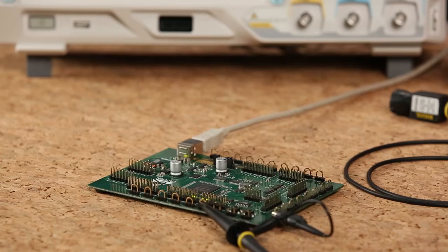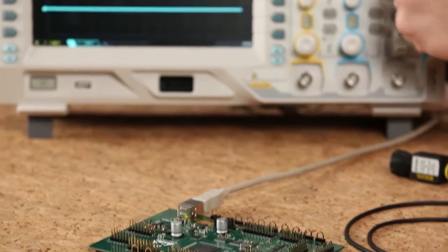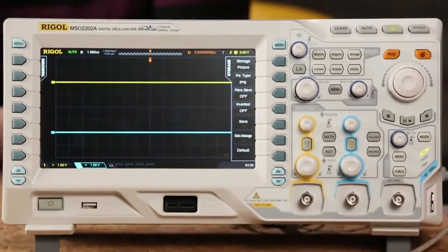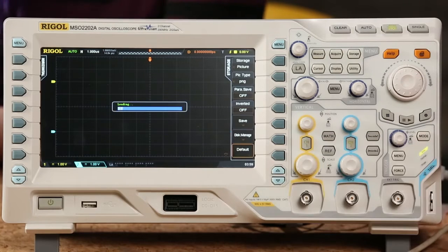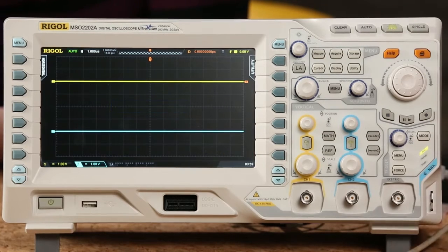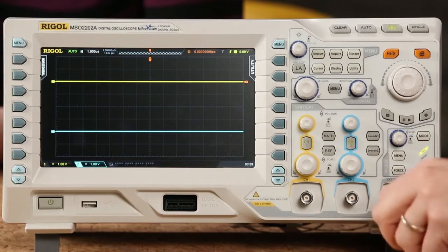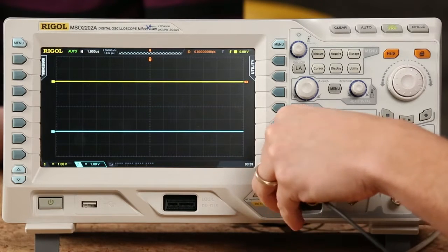So we've got our scope set up in our default mode. It's actually always a good idea to know how to get back to your default settings. So on this scope, you go into the storage menu, you hit the little button called default at the bottom. So this gets you back to everything known good, right in your wheelhouse sort of area.